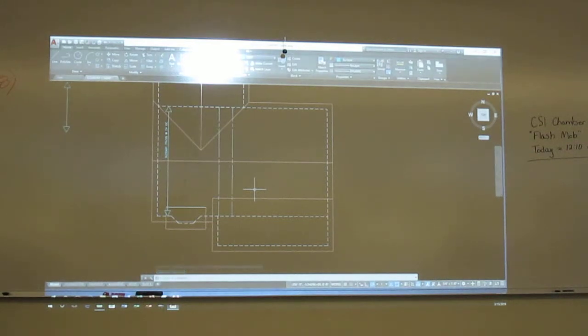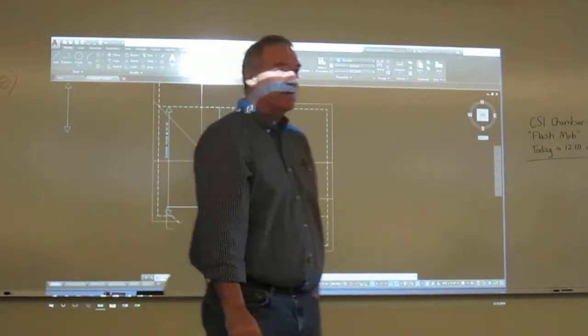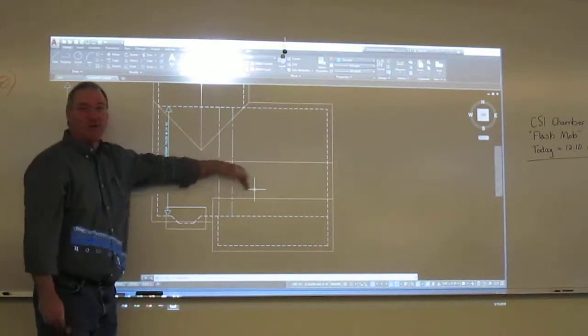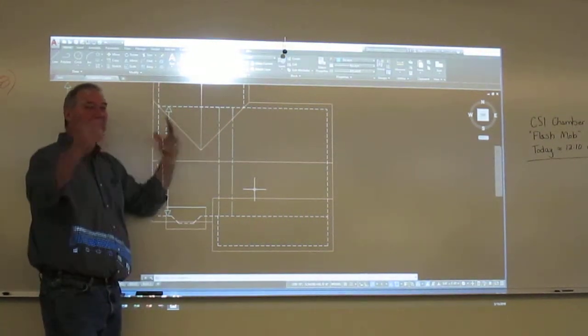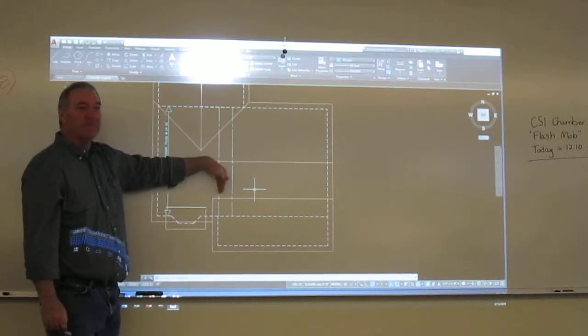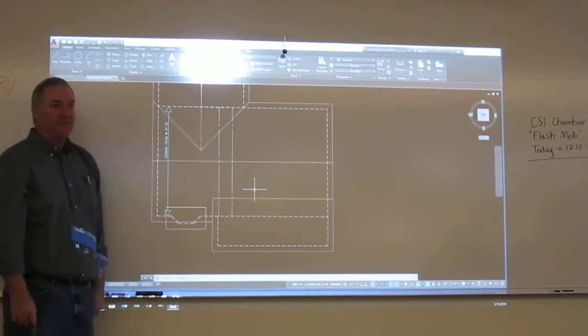So we're just figuring out both sides of the stairs? Yeah, because we're going to have a flat ceiling above that. Now, you can change it if you want. We've got to have a wall in between the master and the living area, right? We don't want that open. Yeah. Okay. Now, we could just have the framers build that wall if we wanted to. But it's better to do it with a truss. It's a lot cheaper to do it with a truss.